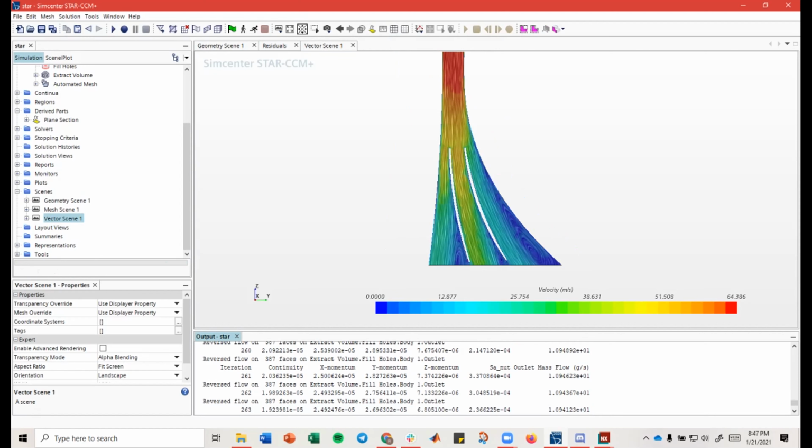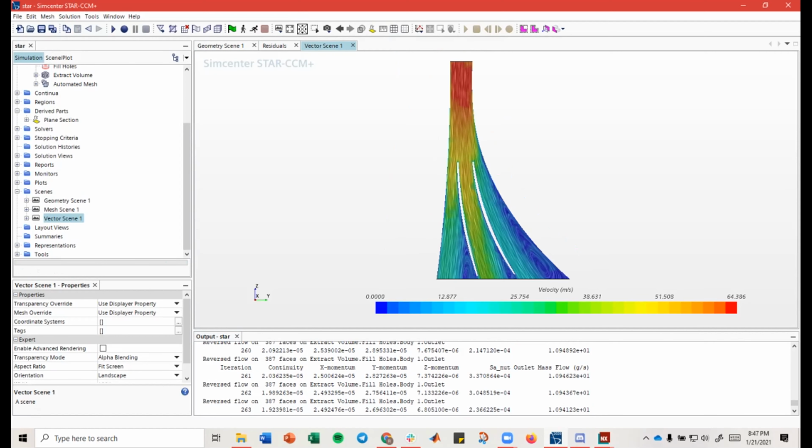And the reason why these values are different from the two sims that I had open earlier is because the mesh might not have been refined as much as possible. This is a pretty big thing in computational fluid dynamics, called mesh independent studies.